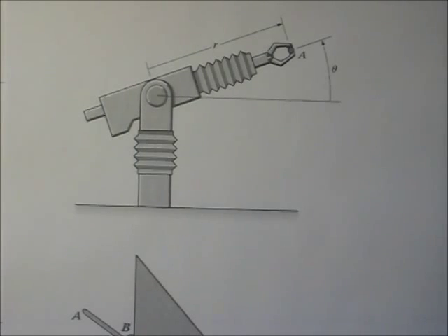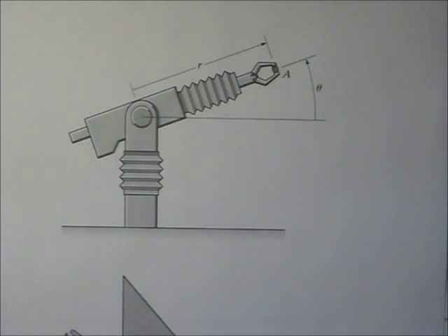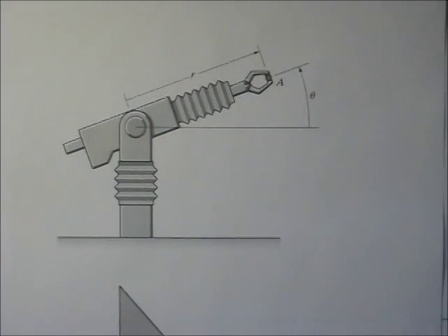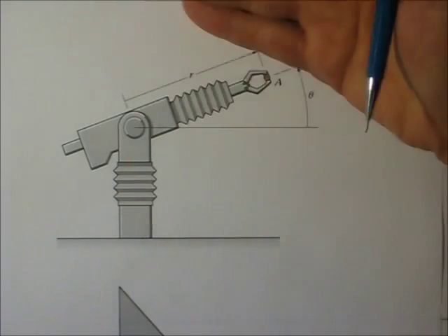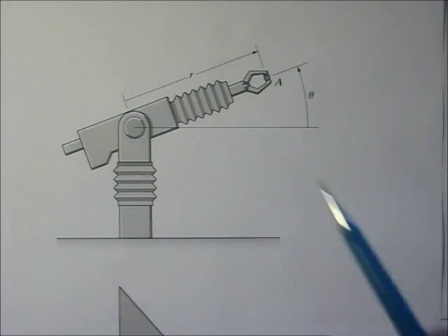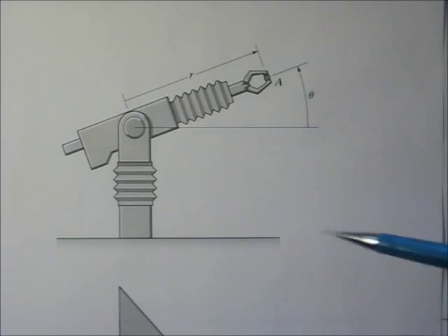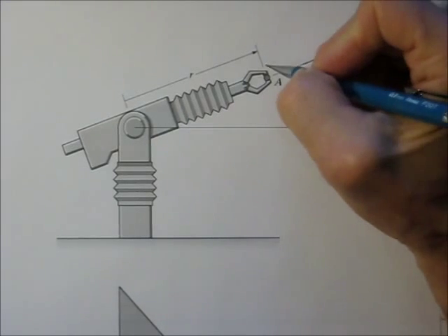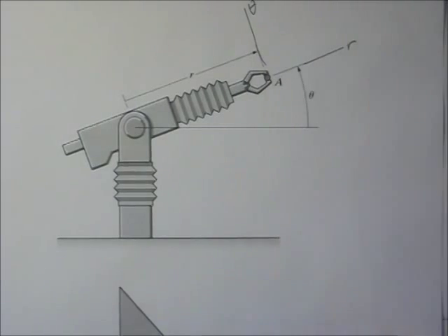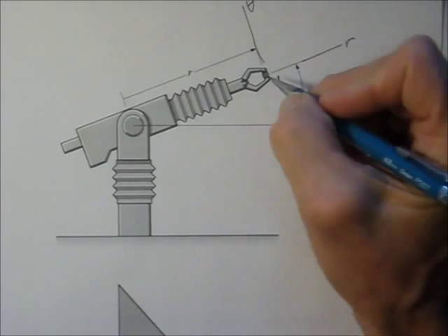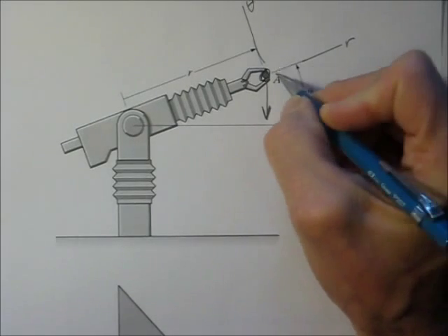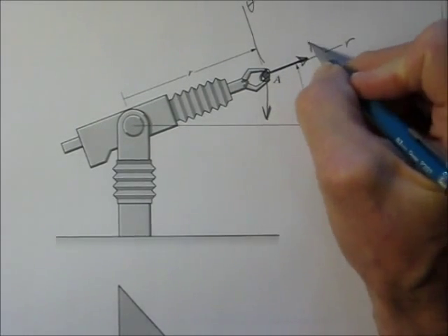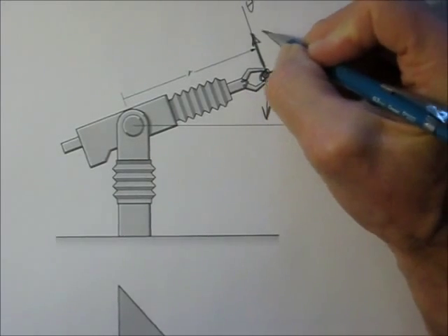All right, what I want to visit with you about is the two general cases of problems we're going to talk about in this video anyway, starting with the unconstrained path. A robot is a good visual of an unconstrained path. This is a vertical configuration. The path is not defined. There will be some R and some theta that is given to you, or you'll have to figure out. What we'll have to do is draw our axes in the R direction and the theta direction, just like we did before. What we'll recognize is there are forces on here such that there will probably be a gravity force coming down, and there will be a force pushing this thing in the R direction and a force pushing this thing in the theta direction.